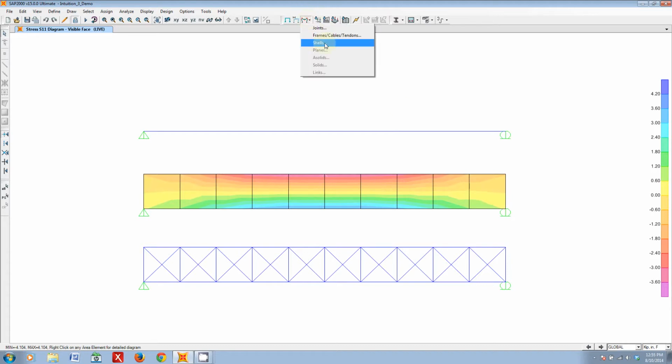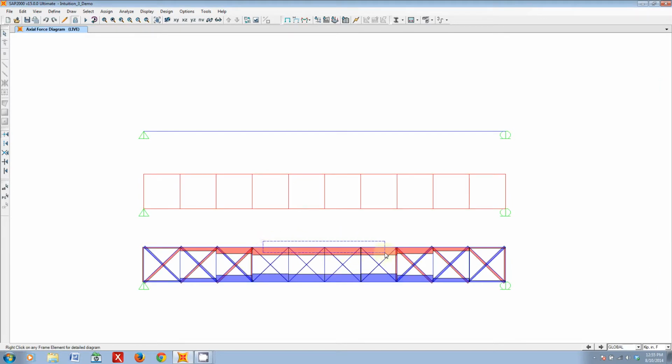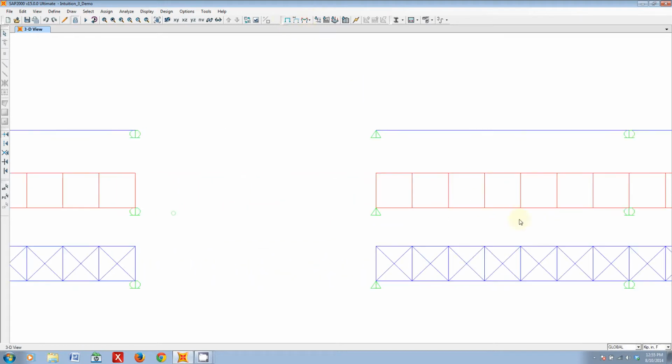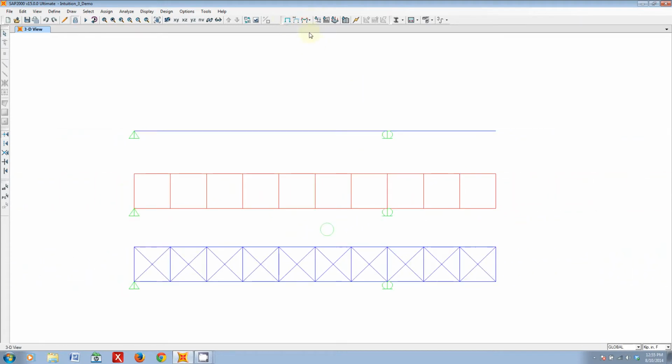Now, what does this look like if we do our axial forces? It basically means that our top and bottom chords carry virtually the same loads within that region. So it was constant axial stress along the top and bottom fibers of our beam, so that means our top and bottom chords will carry more or less constant compressive and tensile loads, respectively, on the top and bottom of our truss. Oh, wow, it's really working great. This is fantastic.